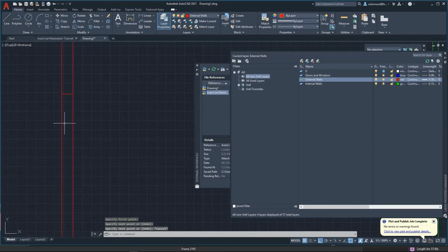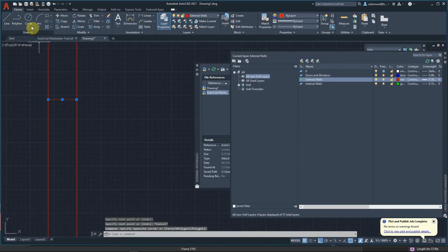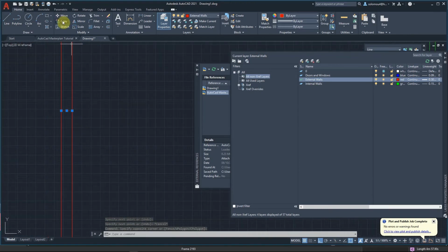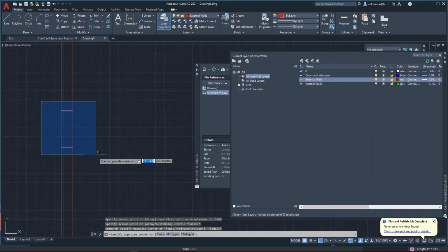Right, so that's where the door is going to start from, and the door is going to, okay, we need to move that line downwards or copy it downwards. We press the copy command after select. So we first select it, we press the copy command, we select the base point, and we drag our mouse down or up accordingly. We can also specify, let's say 1,000 millimeters, so a meter long. So there you go, that has been moved a meter downwards. And that will become our opening.